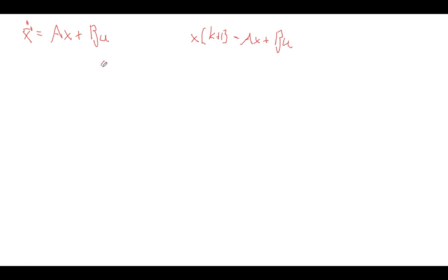So for example, you form a controllability matrix, where you stack the B matrix and then AB as the next set of columns, and you do that all the way up to A to the n minus 1 power, where n is the dimension of A. So A is an n by n matrix, and you have n states. You're looking for this controllability matrix to be full rank. And then there's an equivalent observability matrix formed with A and C.